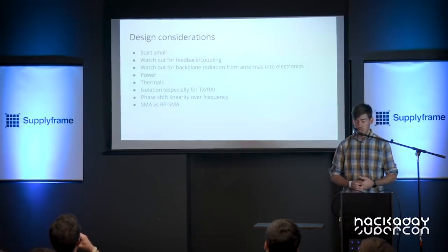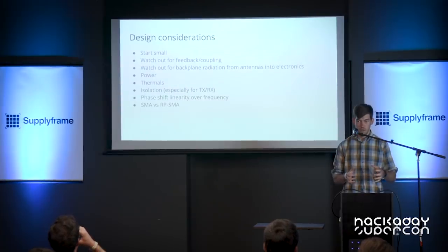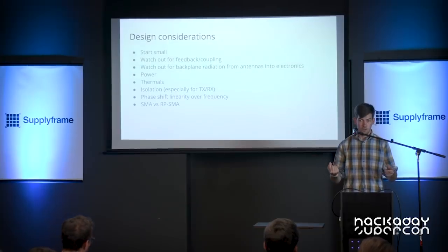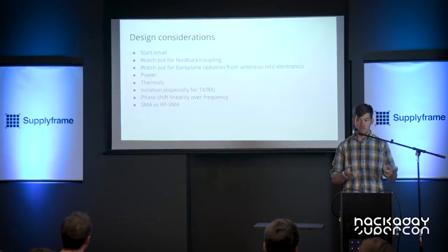Feedback and coupling is a huge deal because you've got a whole bunch of RF electronics and a whole bunch of antennas that are all really close together, which means the antennas are going to couple into each other, and if you don't watch it, the output of one of your ports can couple into the input of another, and you get positive feedback, and stuff will blow up.